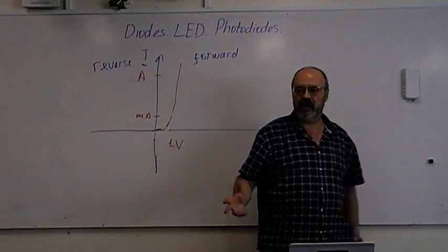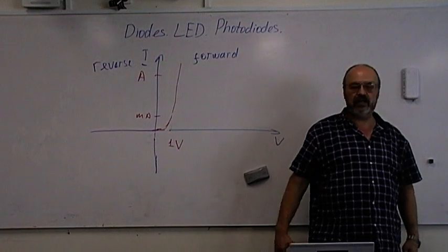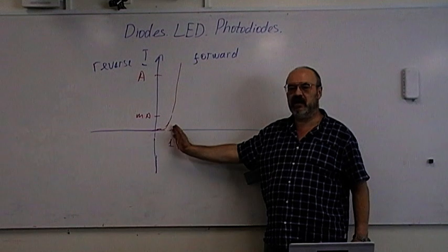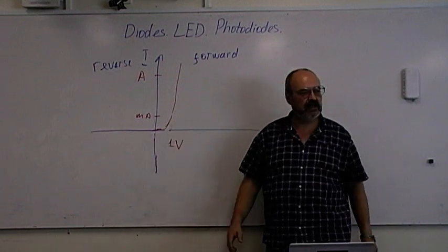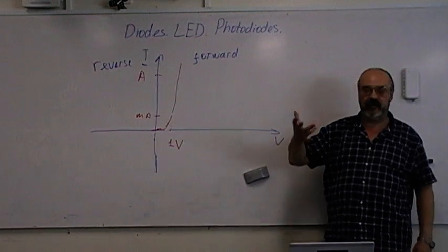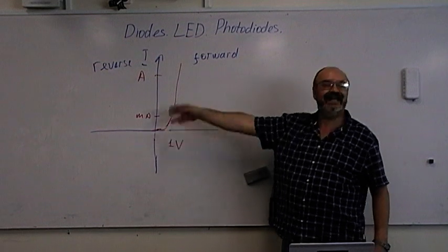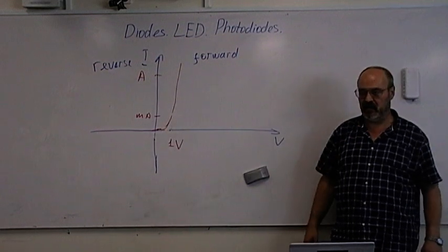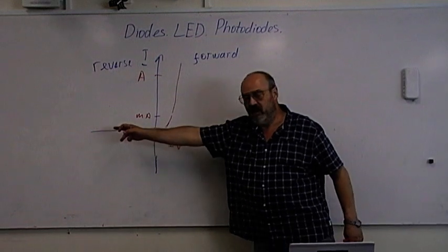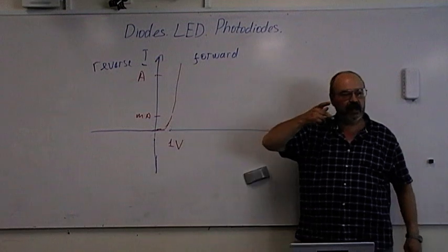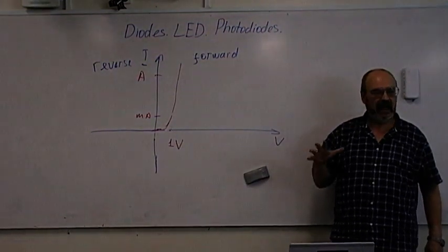Makes sense how the diode works? It allows current only in one direction. As soon as the voltage across the diode in forward bias reaches a certain value, which is different for each type of diode, the diode opens and current can go through. If the voltage is less, or is connected the opposite way, there is no current through the diode. Make sense?